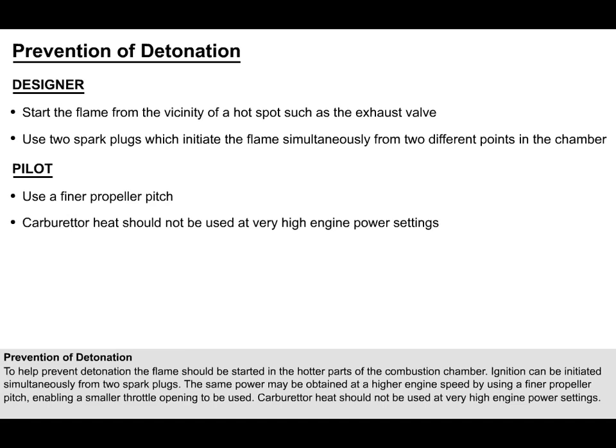Carburetor heat should not be used at very high engine power settings, such as during takeoff. A rich mixture should be used at high power settings.